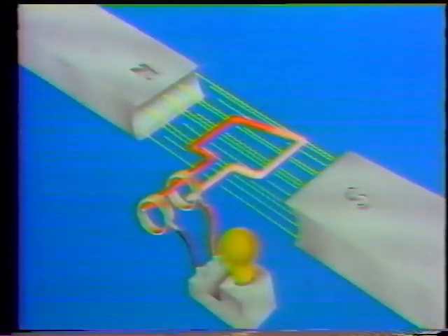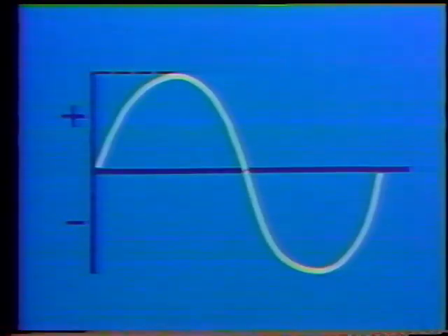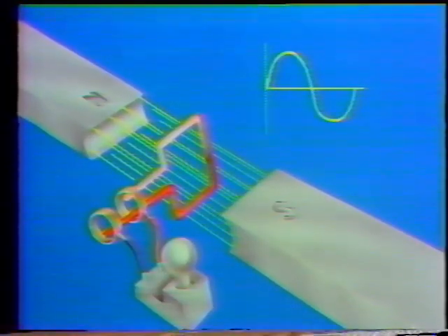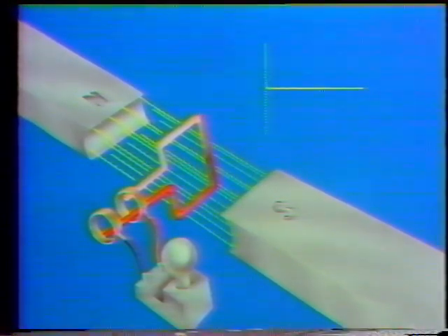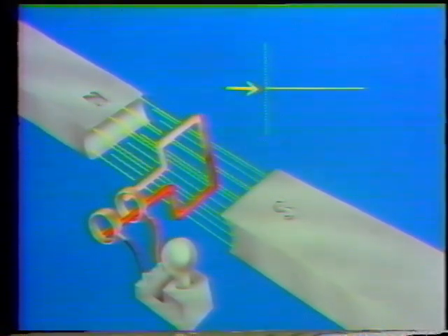Let's look at the way the voltage produced during the movement of the conductor appears on paper. Earlier, we saw a sketch of how alternating current flows. Well, we can plot AC voltage and get the same kind of curve. The kind of curve we have here is called a sinusoidal curve, a sine curve, or a sine wave. It has no sharp bends or straight portions, just a smooth rise and fall. The AC voltage starts at the 0 point on the sine curve, corresponding to 0 degrees for the position of the conductor at the beginning of its rotation.